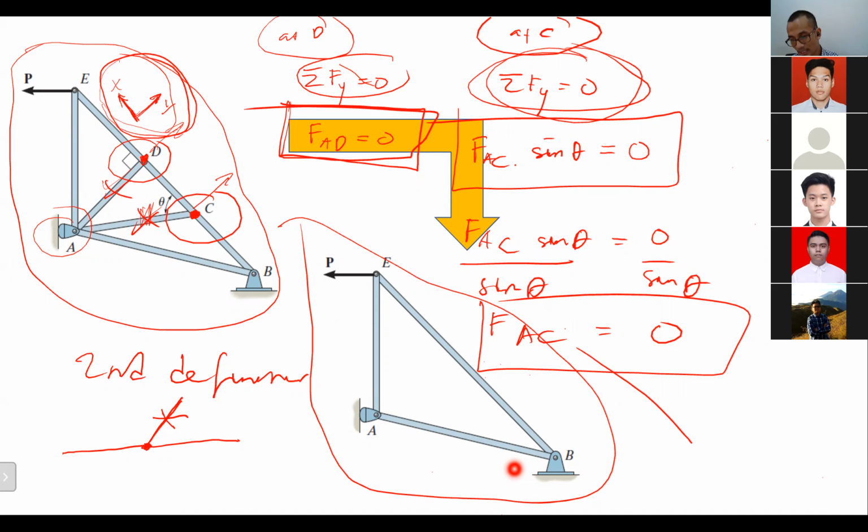If you observe point C, then AC will be zero force. But if you observe point A, you cannot determine that. But if from just one joint you can observe that a particular member is zero force, then delete it. You don't have to consider the other point. Do you get it, Rizky? It must be zero force. Okay.